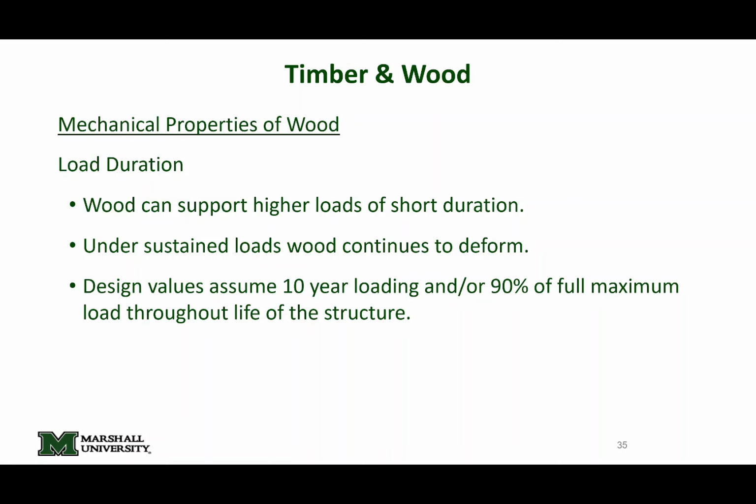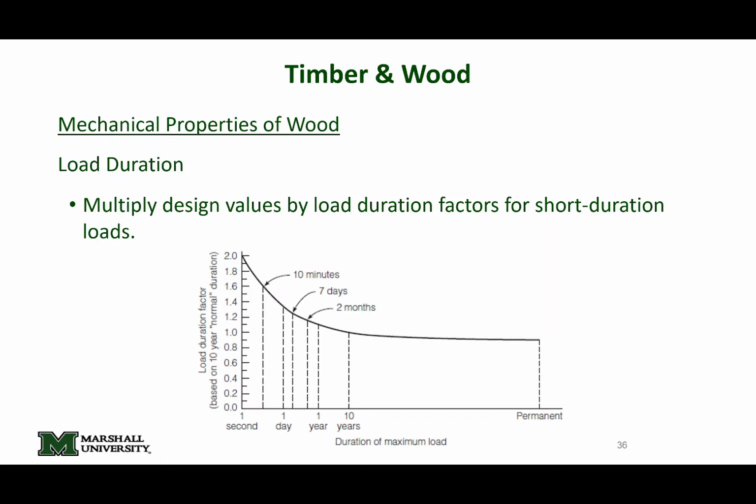Under loads that are sustained over a long period of time, wood will continue to deform. This is a material phenomenon known as creep, okay? If you look at wood's behavior as a function of time, it's almost like instantaneous loads. If you apply a load for a second, the wood is going to be twice as strong than if you leave it on there for 10 years or permanently.